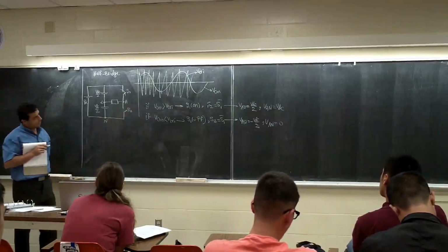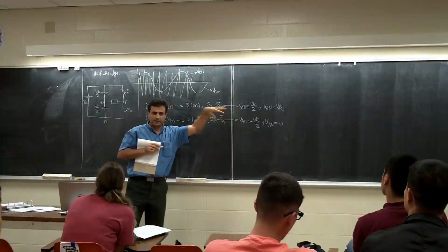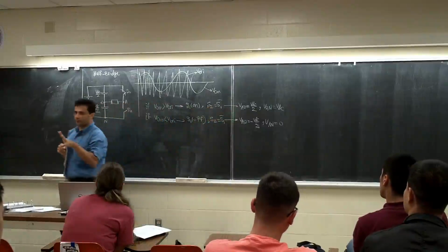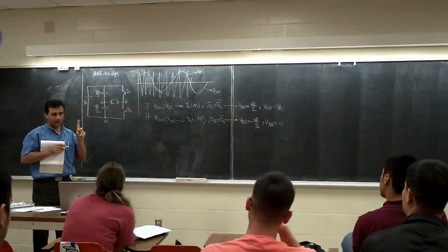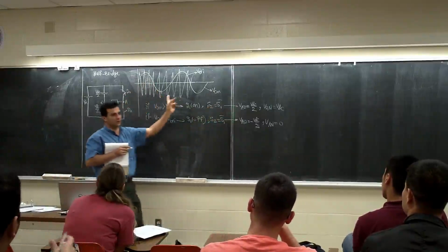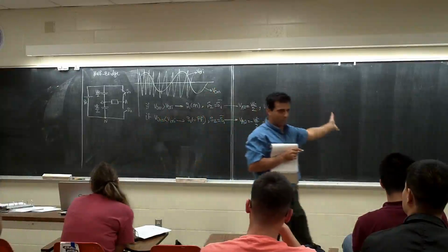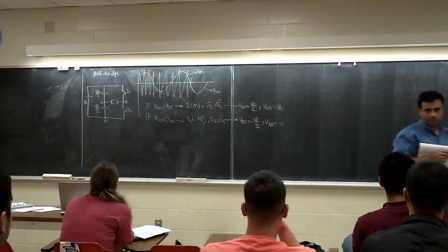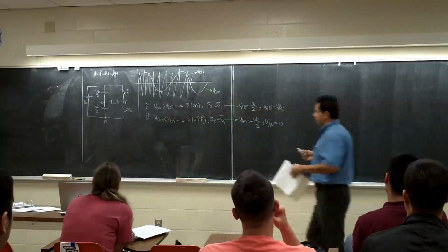Now, let's write the equation. We explained the MA, MF, all those kinds of things. The one that is always very important for us is the fundamental harmonic. We are going to have output harmonics and some voltages, but the one very important for us is the fundamental. Now, let's see how we can find out how much that is.